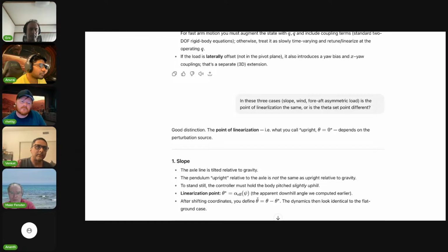It'll just, the conceptual robot will start drifting from the geometry of the physical robot. So the vertical equilibrium balancing point will not look like standing up straight, that kind of thing. And generally something as simple as a PID controller would be trying to get it to stand up straight. It wouldn't be stable at a weight back. I mean, if you just had a PID controller tuned for the nominal vertical, and then you randomly added a manipulator arm and loaded it with a small load, that would just fall over because it has the wrong assumptions about the world.